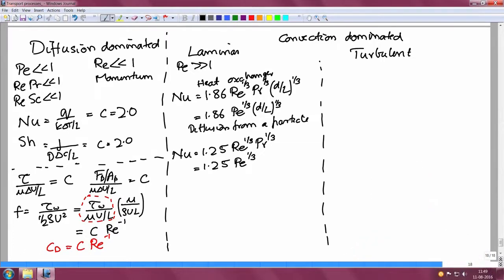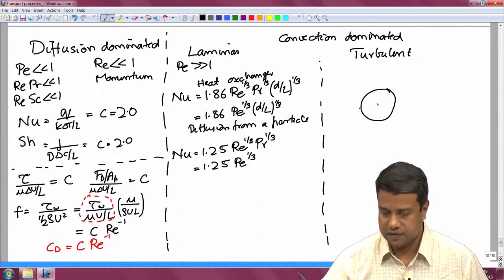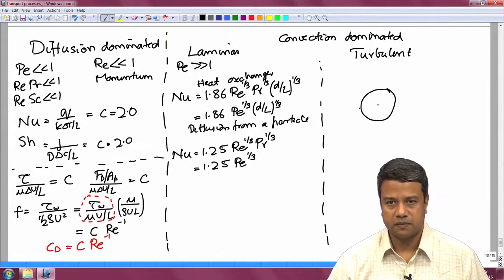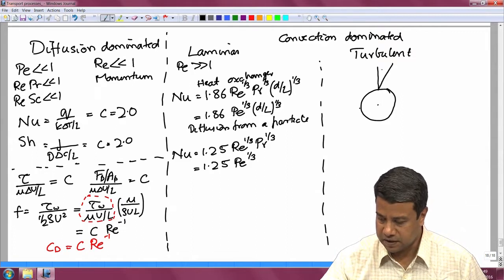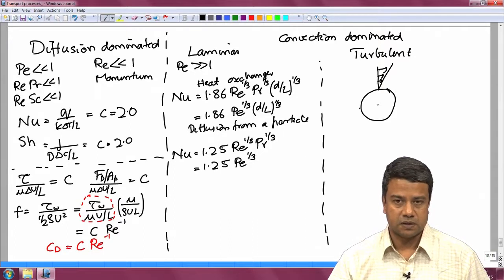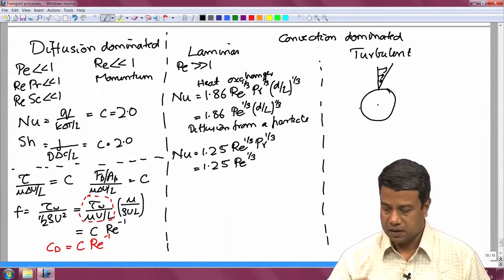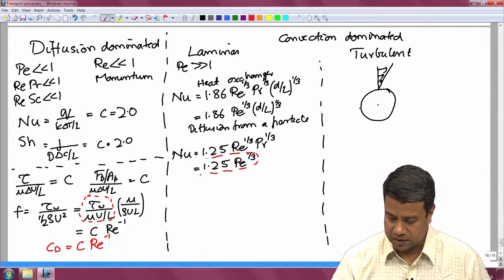But the other thing that it depends upon is the details of the fluid velocity field. For example, if I had a solid particle, I would require that the velocity of the fluid at the surface of the particle has got to be equal to the velocity of the particle itself. If I am sitting in a reference frame on this particle, then the fluid velocity field has to decrease to 0 at the particle. This is a no slip boundary condition. In that case, you get this relationship.